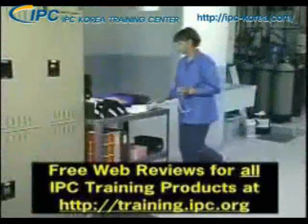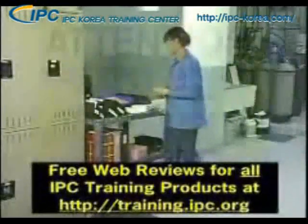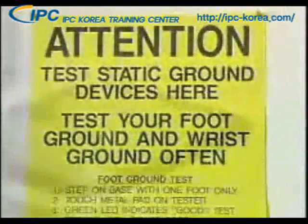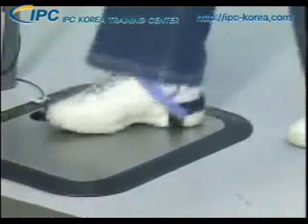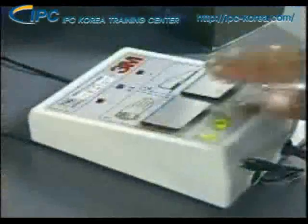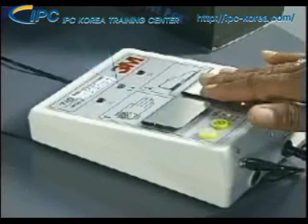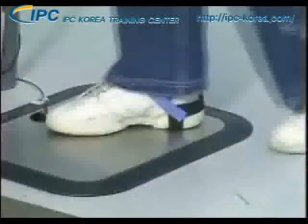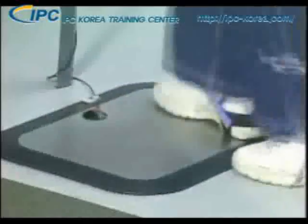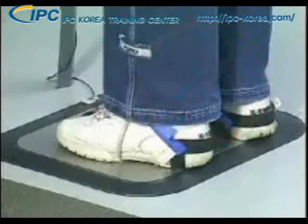Shoe grounders and wrist straps should be tested at regular intervals to make sure they are working properly. Your company will let you know where and how often you should do this. When testing shoe grounders, place the foot with the strap on the metal plate and press the test button. The pass light indicates that the device is functioning properly. If wearing straps on both feet, test each foot individually. Testing both feet at the same time will not indicate a failure unless both straps fail.